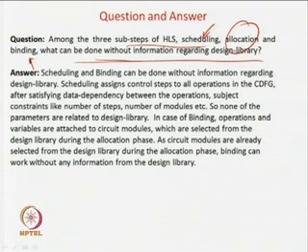Already we have seen that we have used a very fast multiplier, but slow adders, based on the timing requirements of the multipliers and the adders, and based on that we decided that it is good to use a fast adder, a slow adder and a fast multiplier. So, this allocation stage looks at the frequency, power requirements and all.